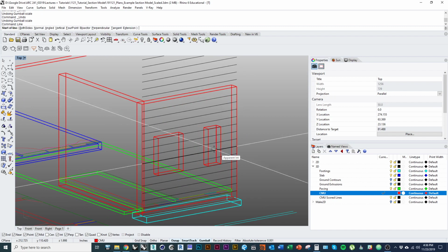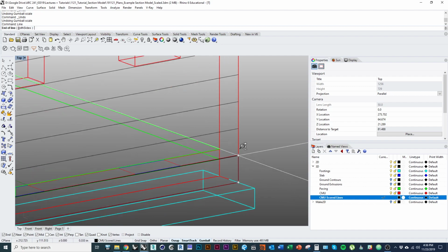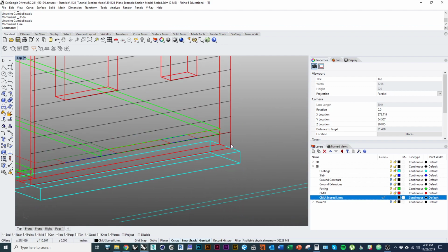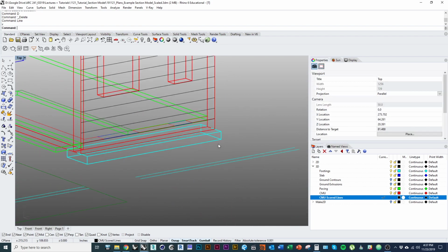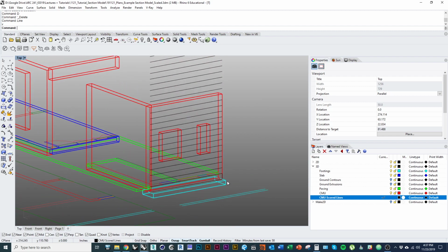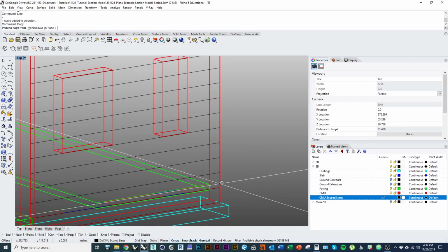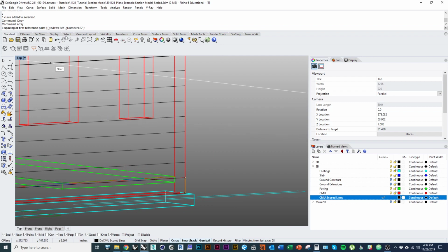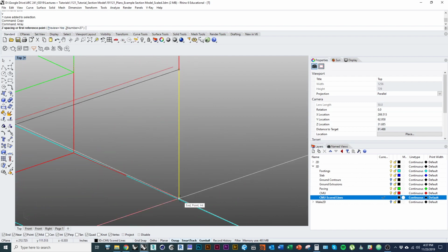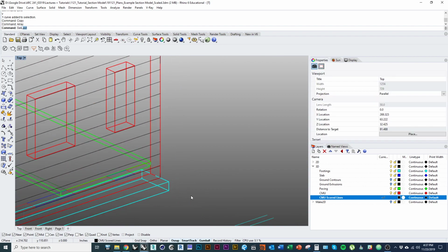All right, and the best way to draw the horizontal coursing is we'll go back to that scored line layer. I'm going to draw a vertical line. Actually, let me just use the command line vertical to make sure. There we go. All right. And let's see. I'm going to make a copy of that line. Or I suppose I could array it all the way up. So again, X direction is set to 1, Y 1, Z is 27 still. And the start point will be the end of the line, end point will be the other end, right? And then press enter. We go, select last.